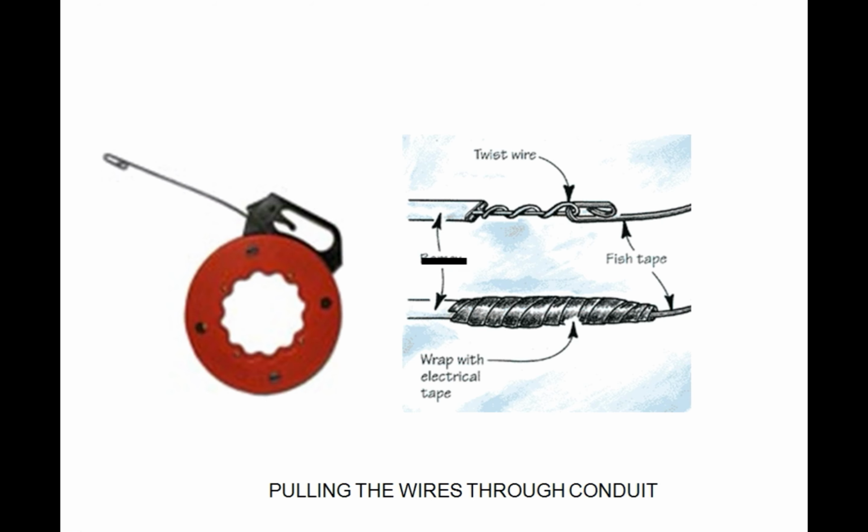Generally, part of the electrician's job is running cable through these conduits, or EMT, or through the Greenfield, right? They need to get the wires through, and it's impossible to just take the thinner wires, the number 12s or 14s, and try to shove them through dozens of feet to get to the next opening where you can pull them. So they devise a couple of tools, and you generally either snake it or mouse it. Those terms can be used interchangeably.